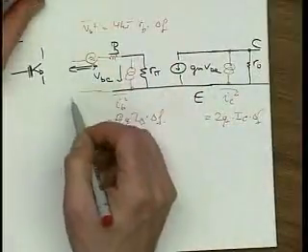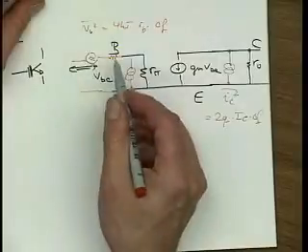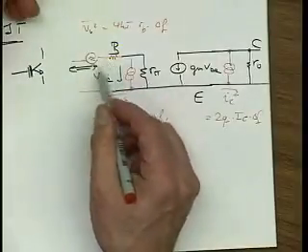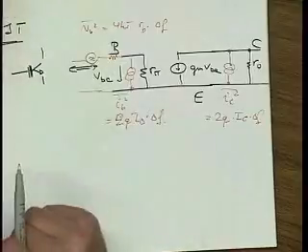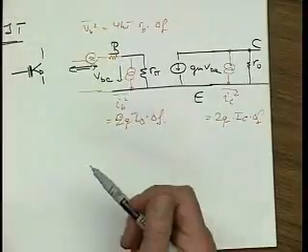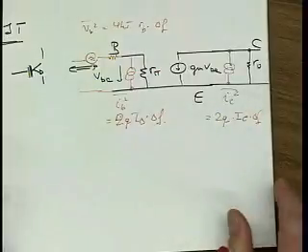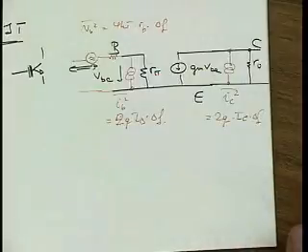If you drive this from a 50 ohm source, well, then the source may have a lot less noise than this base resistor. Okay, and we'll see later that even if you do feedback and so on, you still get the noise. You don't get the attenuation, but you still get the noise.